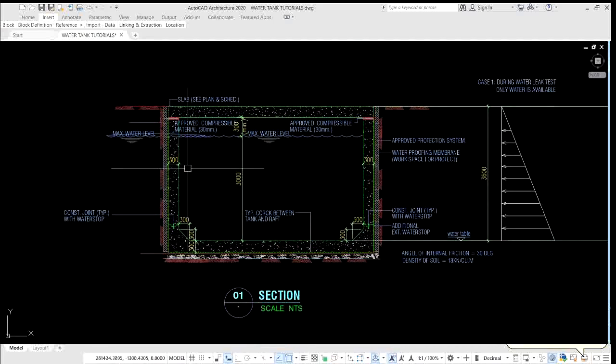As you observe, the initial thickness of the wall is 300 mm, but that's not the final size yet. Our final size will come from our analysis using ETABS and other parameters like crack width. Also, the height of the water is restricted to 3 meters with a minimum air gap of 300 mm.